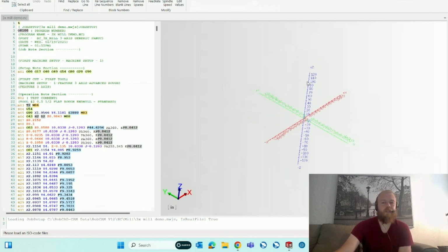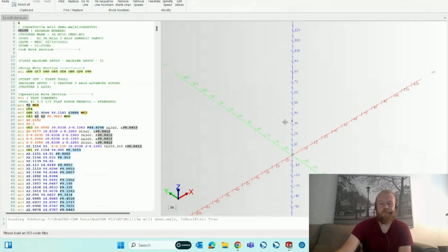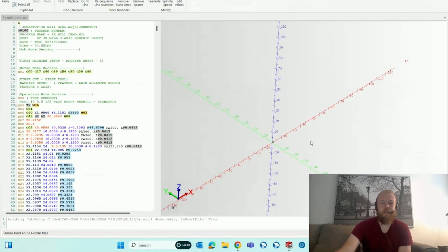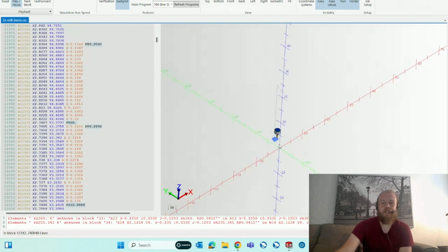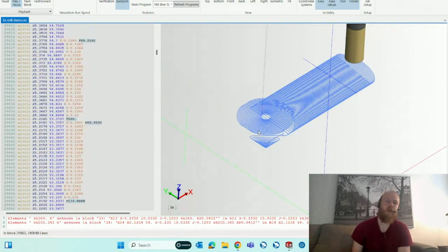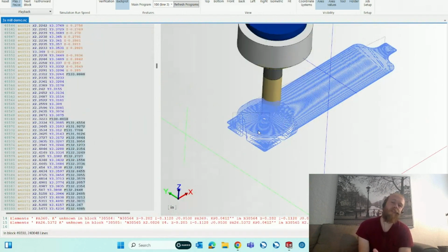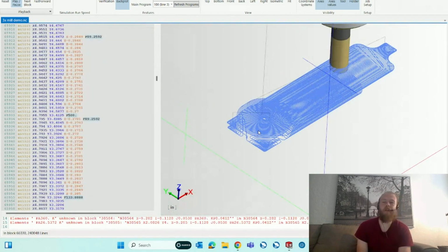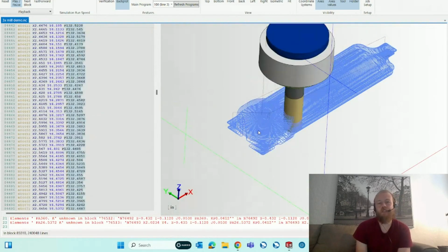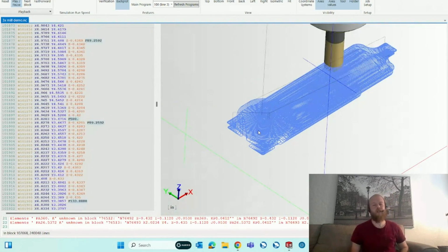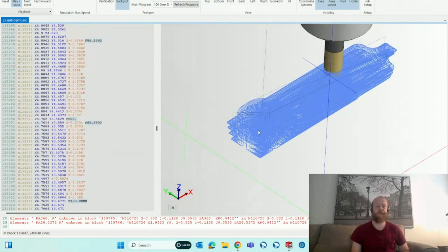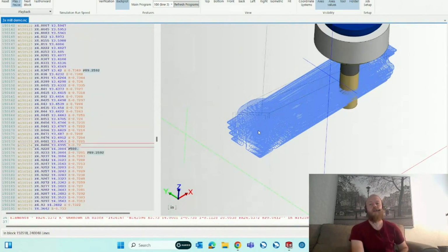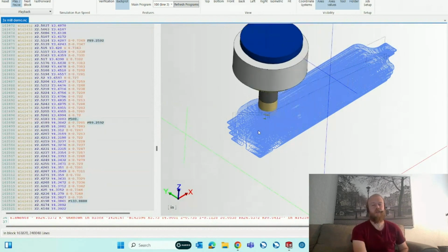We also offer, this is in the NC Editor Pro, not really something I was necessarily thinking of going over today, but we can simulate in NC Editor. Now the simulation in NC Editor is in the NC Editor Pro, but what this is doing is it's actually reading the G-code line by line and backplotting the toolpath that way. So if there were any discrepancies in the G-code, anything incorrect, a Z move that's going to gouge down into the table or something like that, it's going to show you because it's going to read the G-code in this